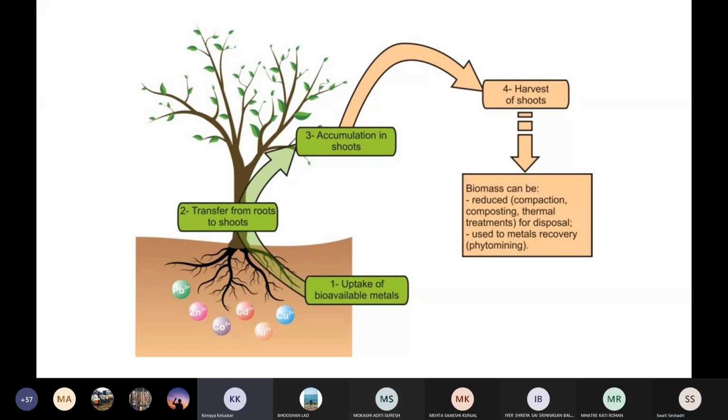Yeah, so just to add to what Swati said, in your phytoremediation, as she rightly mentioned, there are plants which are used to absorb all the sludge. Whenever all your fecal matter, whether it's in the form of black water, which comes from your water closet, or gray water, it first empties itself into a septic tank. Now, a septic tank is more like a settling tank. We will be showing you those diagrams and also giving you the sizes of the same.